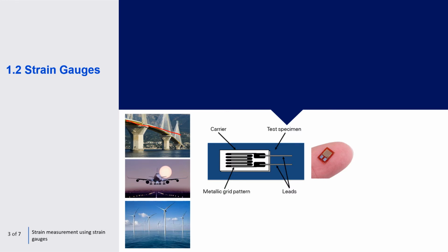And then here you've got this metallic grid on the strain gauge, which is formed of foil, with these being parallel to one another. So when undergoing strain, let's put this under a force, it'd be under a tension force. These little parallel foil strips are going to stretch or increase in length as they undergo strain. And then you've got the leads here for positive and negative. The cross-sectional area of this grid is minimized to reduce the effects from Poisson's strain, as we talked about earlier.